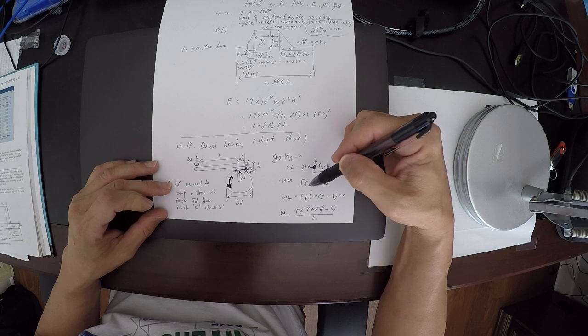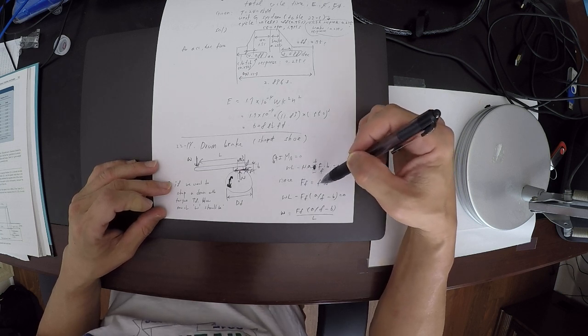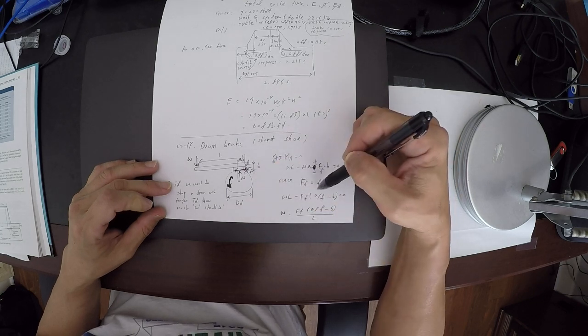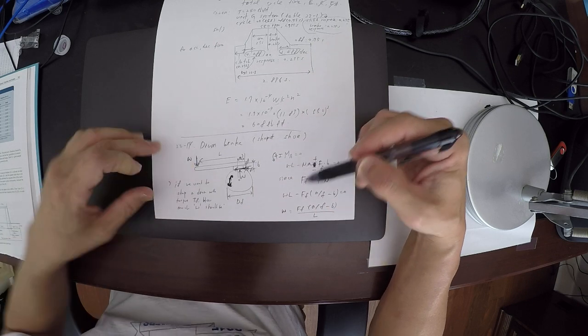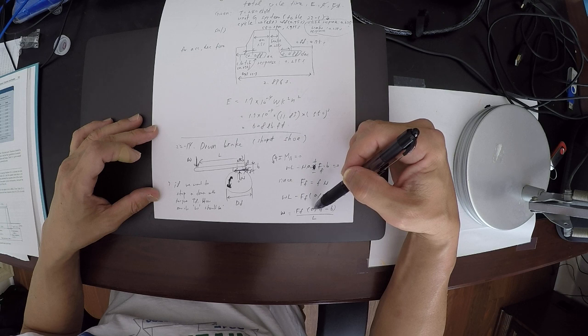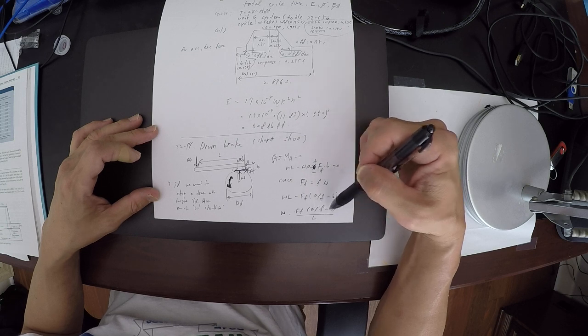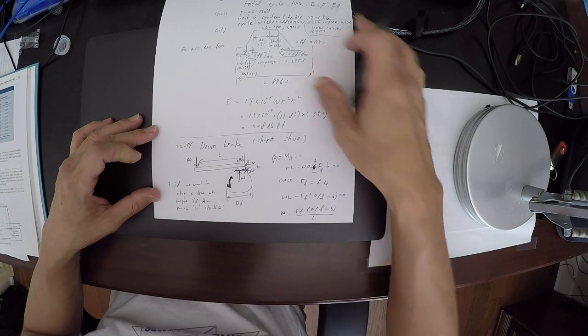And then because again the friction is the friction coefficient f times the normal force N right here, we can calculate the W, which is the force you need to apply, as a function of friction force, and then the geometry of the lever system A, B, and L, and then f, which is the friction coefficient. Okay.